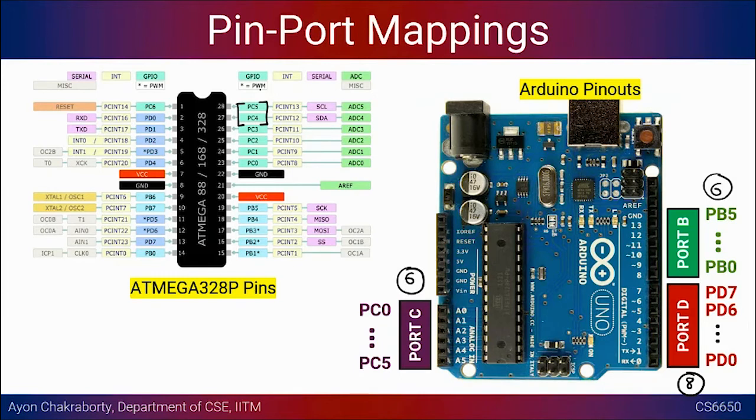You can turn on an LED, or you can have this input go to a speaker, right? Or you can actually generate a signal using these two pins. And at the same time it can also be used for I2C, right? So this is the serial clock and serial data, which could be used to interface some kind of I2C bus enabled sensor.